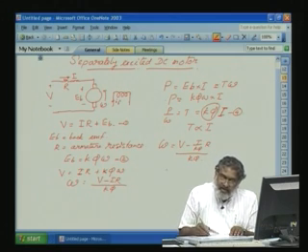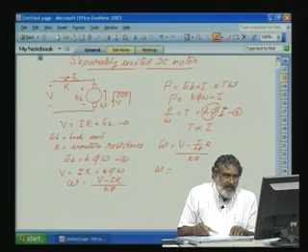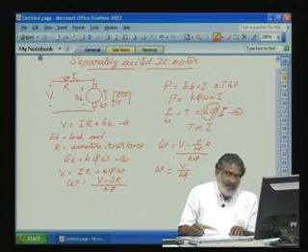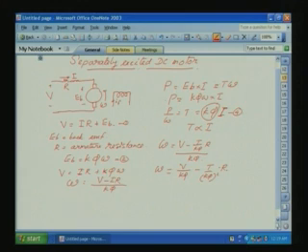Okay. This we can again write as omega is equal to V by k phi, this is a constant, minus T by k phi whole square into R. So, we got a relation between omega and the torque T. Okay. This is this one.